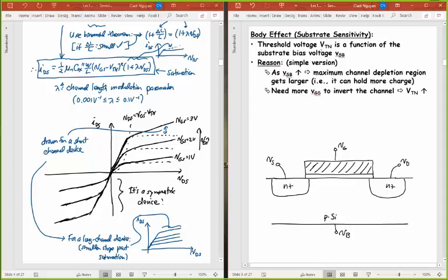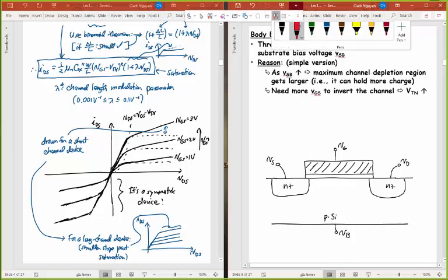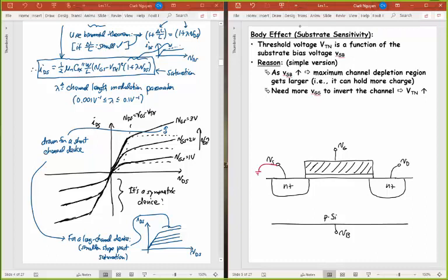What you know about it is that it is the voltage that the gate voltage has to get over in order to form that channel. So if I take this cross-section that we've been looking at for a while, and put some voltages around this, I'm going to put ground here, and I'm going to put a VG on here. Let me say the VG is greater than VTN. So say I put a VG here that's greater than VTN. And VD, I can put any VD. I could put ground or whatever VD I want to put in that.